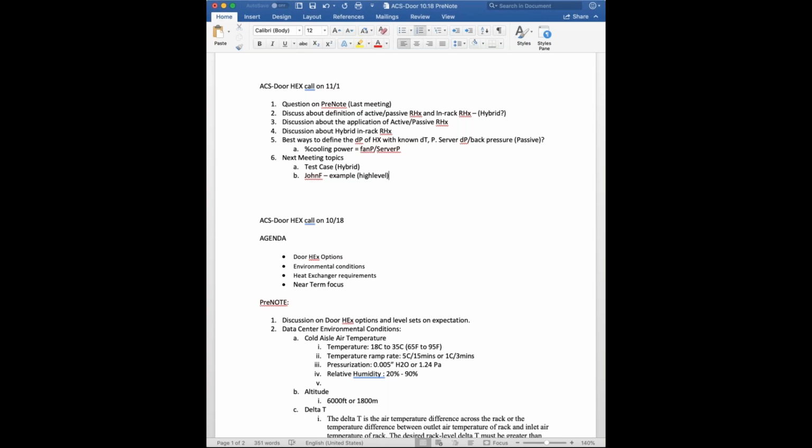So typically, when the server equipment sucks in the cold air from the front and blows out the hot air to the rear, there has to be a tight sealing between cold and hot air. If the sealing is not proper, the hot air could move to the front and not be pushed over the heat exchanger. Create the sealing within the rack.